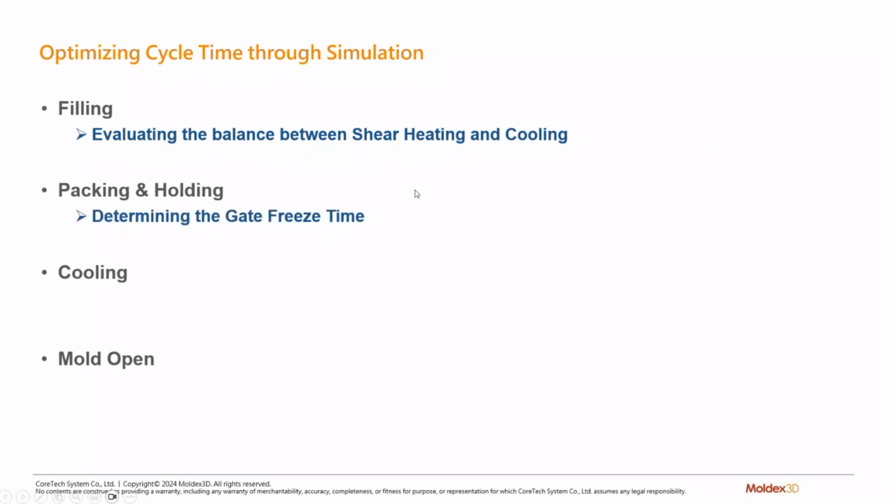Next, for packing and holding time, we will determine the gate freezing time in Moldex 3D Studio. In cooling, which happens to be the chunk of the time, we'll look at how to use the time to eject result in Moldex 3D.